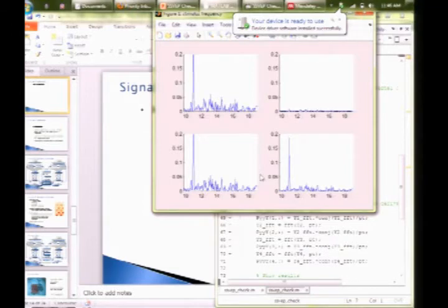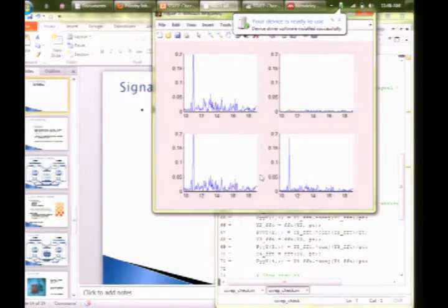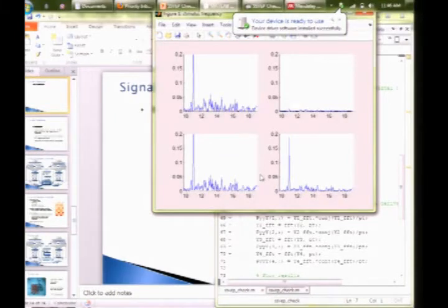How much time? It depends on the person, but basically what we do is we say if this peak is 5 times bigger than the mean of the rest of it, then we classify it as that signal. It also depends on the ambient light, but it happens in about 1 to 3 seconds if it's dark enough, and if there's too much surrounding light, it happens in about anywhere from 3 to 15 seconds, something around that.